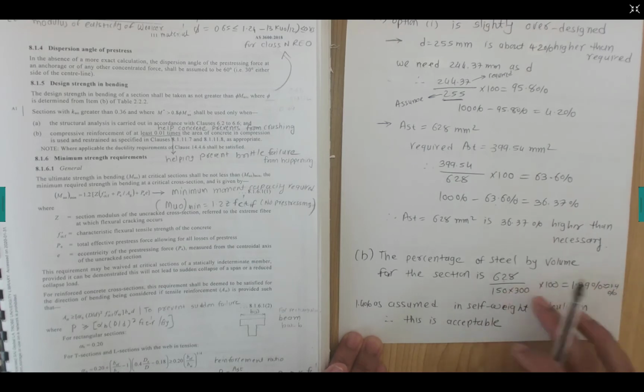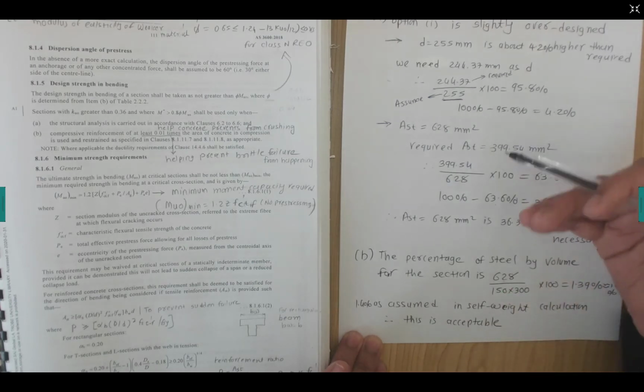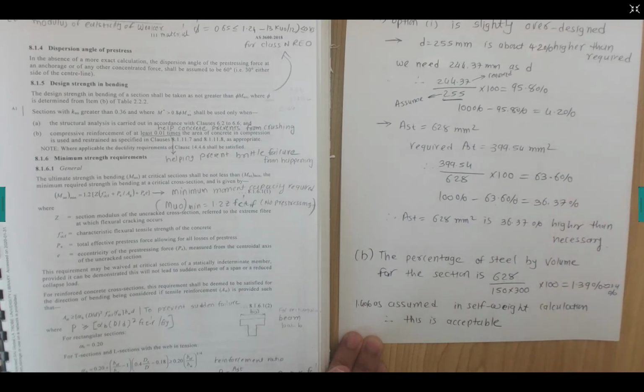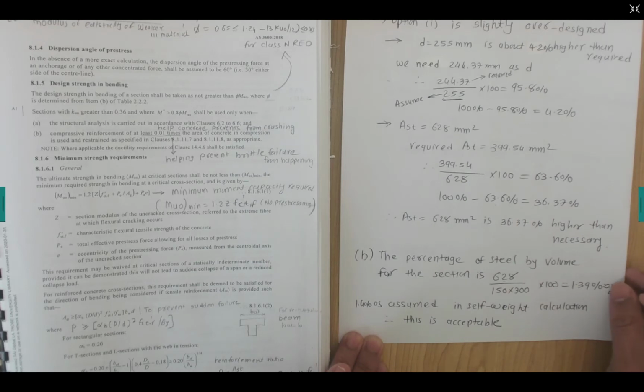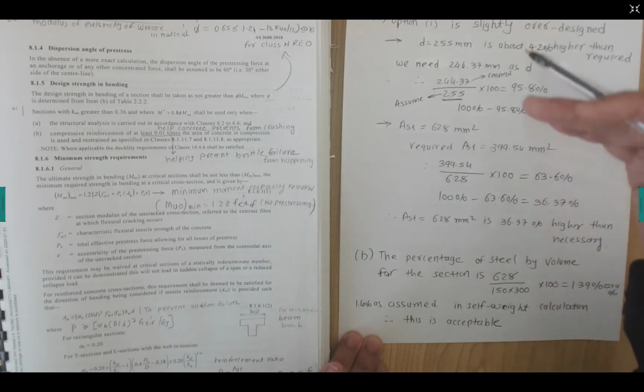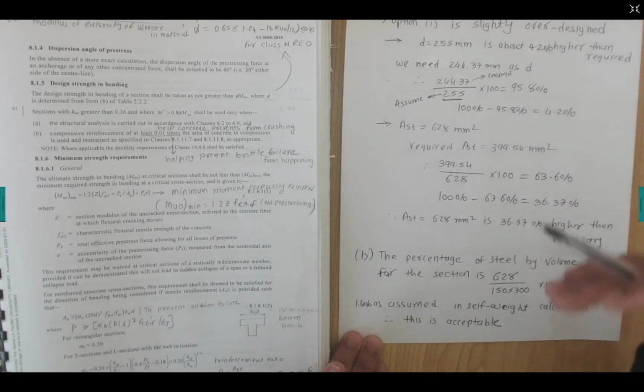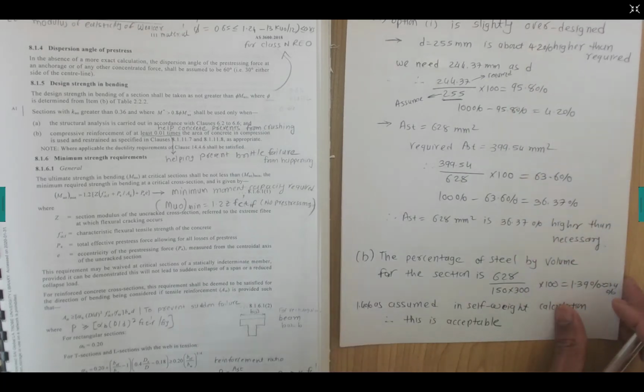If this difference is very big, you should use the actual reinforcement and repeat the procedure again, making sure all the calculations are correct. Hand calculations would be very time consuming, so I suggest developing an Excel spreadsheet where you can put all these equations and change the numbers.